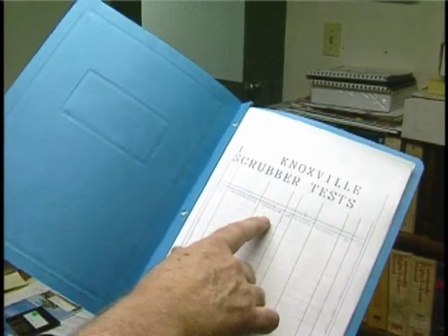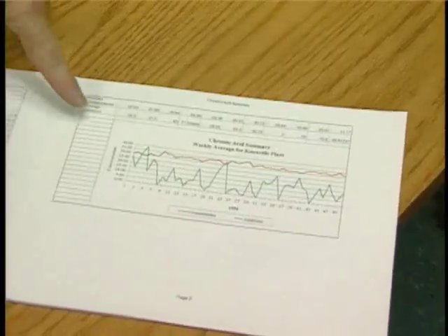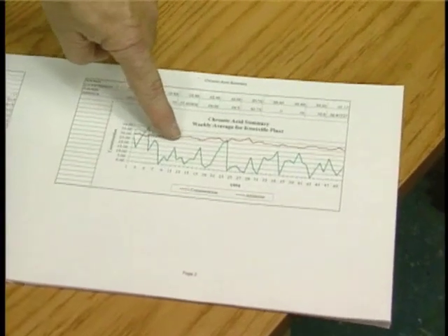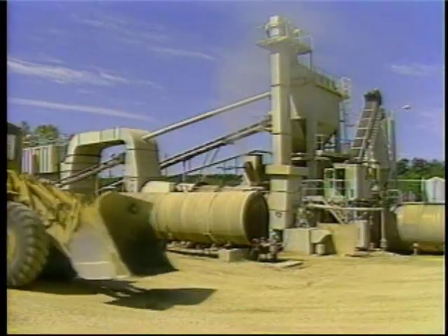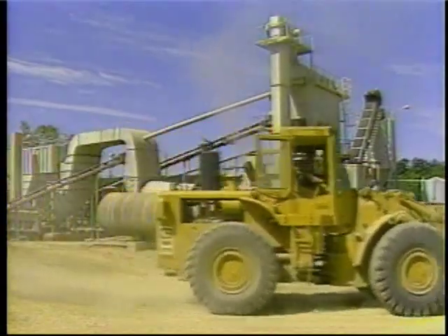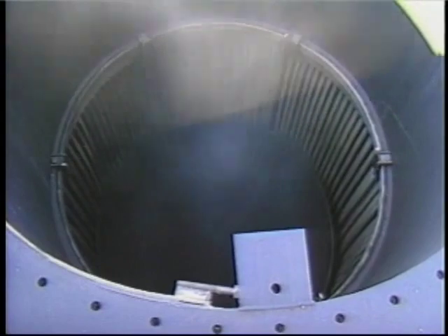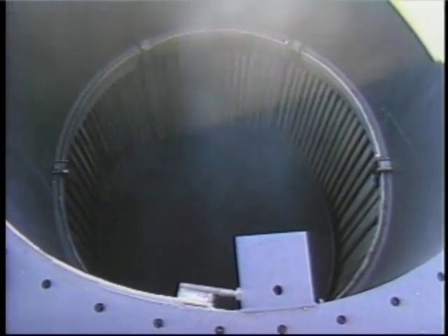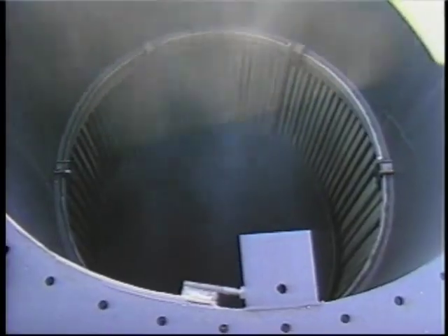In addition, parameters that influence performance should be evaluated to see if there are shifts from the baseline values that can indicate reduced collection efficiency. The most direct indicator of system performance is the opacity of the outlet gas stream. However, since the gas stream is usually close to saturation at the outlet of the scrubber, the presence of condensing moisture may make the observation difficult.